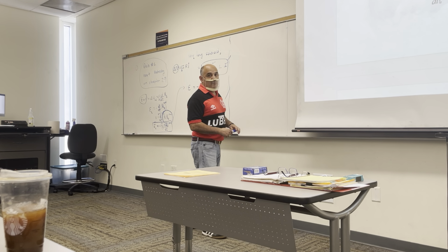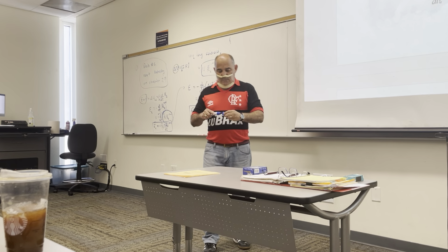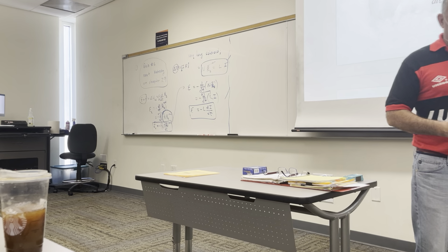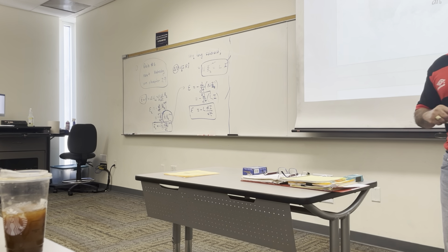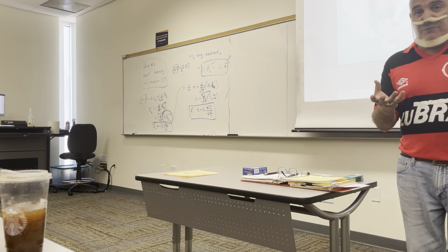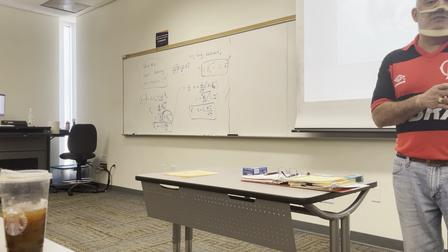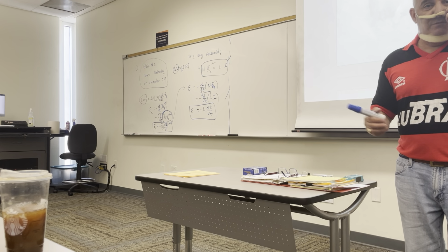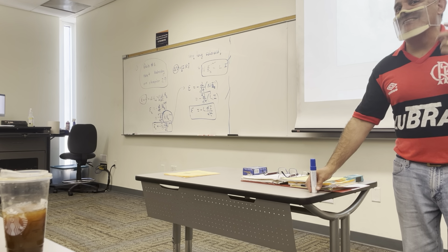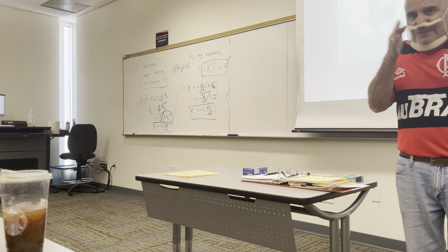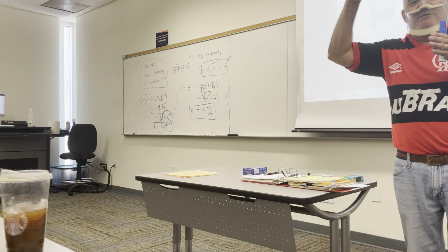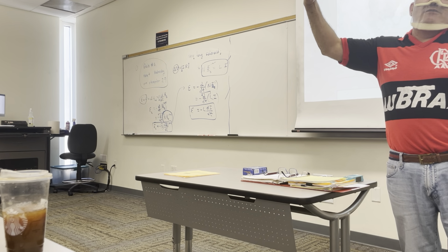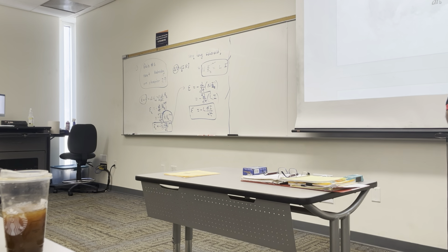Professor, just to be sure, I was writing, inductance is like the resistance to a change in current? So it wants it to stay the same, like constant? Right. So when you start a current in a circuit, initially there's no current in the circuit. When you throw the switch to the on position and then you get a current of 5 amps, the current doesn't go instantaneously from 0 to 5 amps. There's a delay. It takes a while to get to 5 amps. And the greater the inductance of the circuit, the longer it's going to take to get to the final 5 amps.